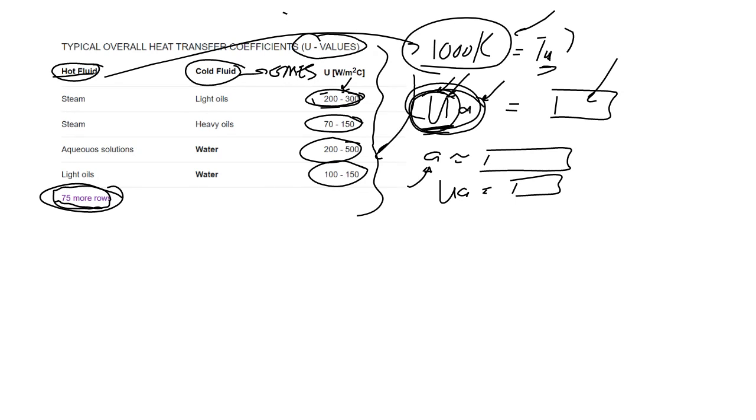The truth is that you actually have to calculate that U, and you have to specify your reactor, and that will affect A. The diameter of your tubes that you specify, the number of tubes must all add up to the amount of catalyst that is needed. So what is fixed in your assignment is the amount of catalyst that you are needed, linked to the 10 cubic meter reactor that must be designed and the bed density that is specified. Right. So I don't see any questions popping up, so I'm going to go to the next slide.